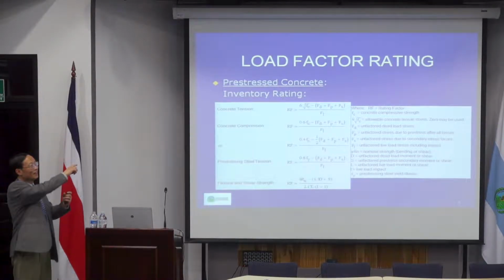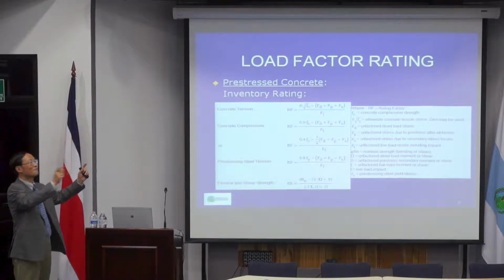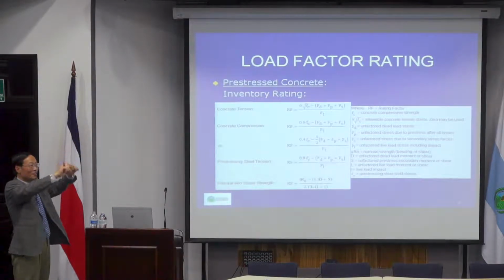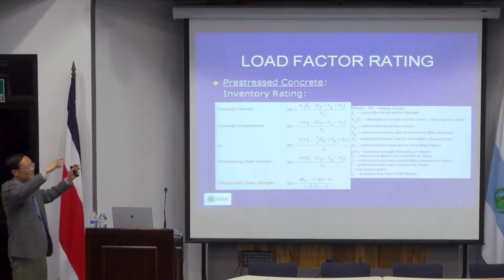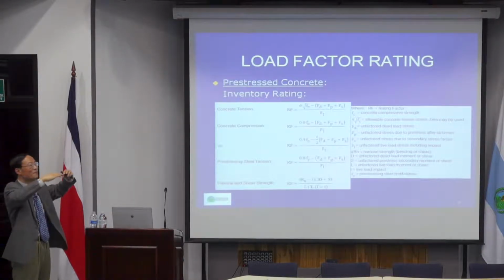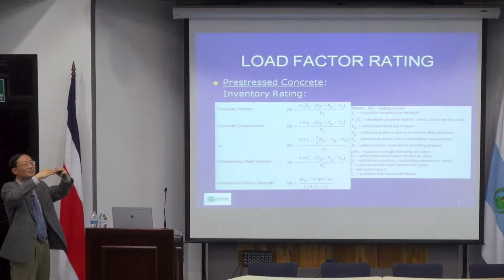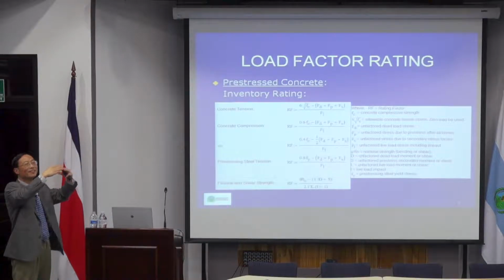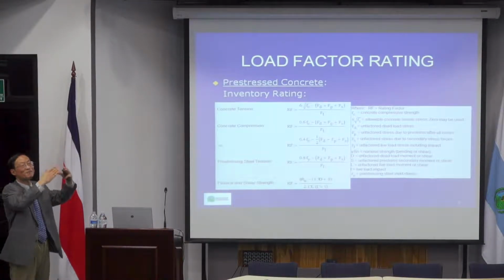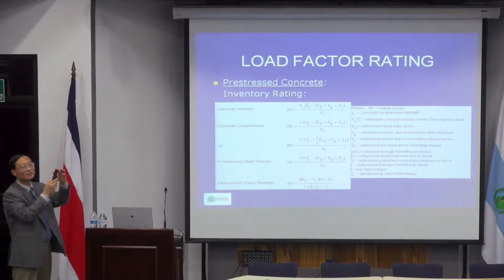For example, if you have a continuous two-span beam, with a support at each end and a middle support, and then you have a cable which represents a shape of bending, when you pre-stress it, if you imagine the girder has no weight, the whole girder will try to bump up to that shape. But because of the weight, it balances out and does not actually bump up, so you still have a support in the middle. But the middle support, before post-tension, if it's 20 tons, after post-tension it becomes 10 tons because of the weight. Otherwise, it will go up.